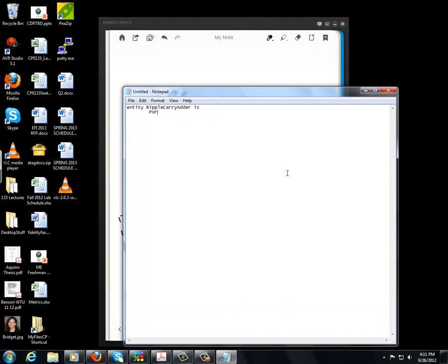Alright, then we define our ports. We have port A, which I'm saying is an input, and now it's a standard logic vector type because it's not just a single bit, it's going to be 3 bits, and to denote that it's 3 bits we say it's 2 down to 0, meaning it's bits 0, 1, and 2 representing 3 bits total.